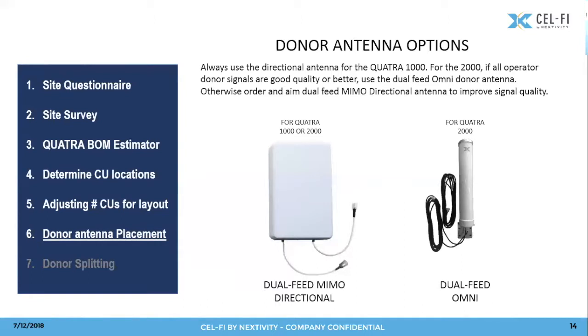Any place where you want to try to clean up the signal to noise ratio, go with a panel antenna. You're not so much using it for gain. In general, you're really using it as a filter, because you want to reject signals coming from unwanted towers that are actually interfering and causing your signal to noise ratio and your capacity to drop.